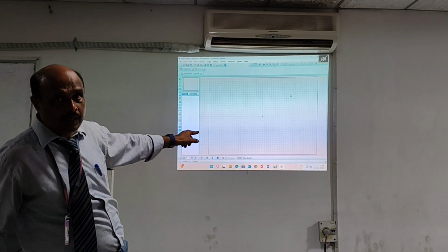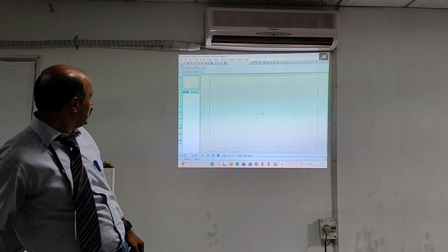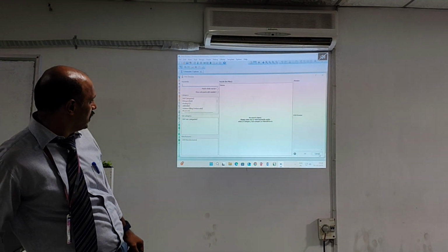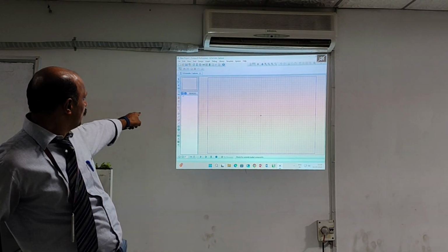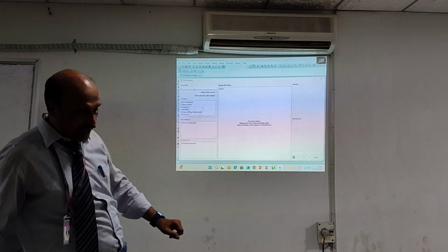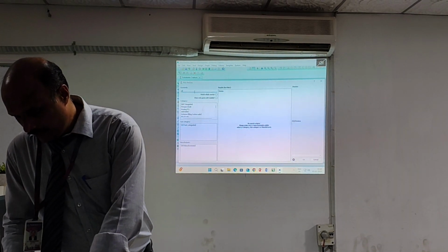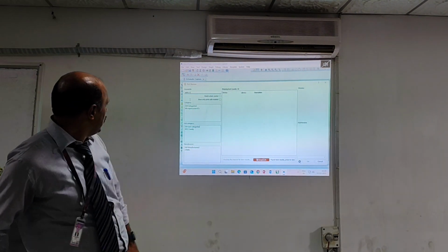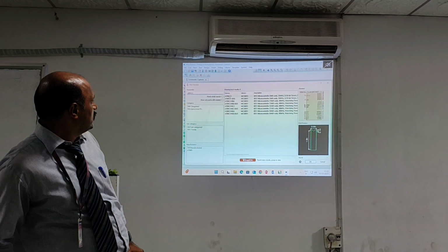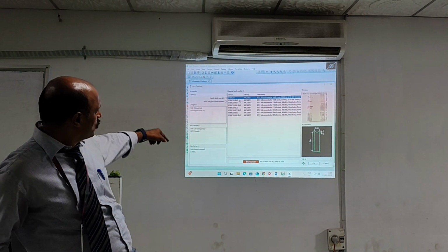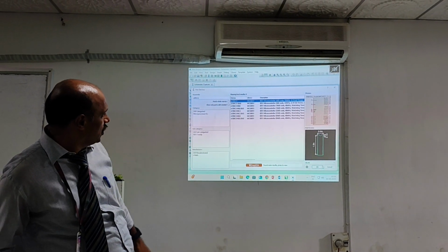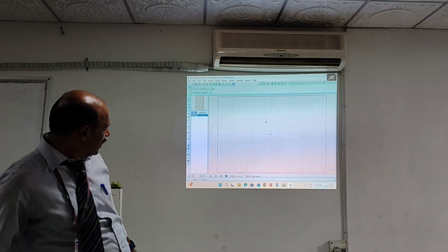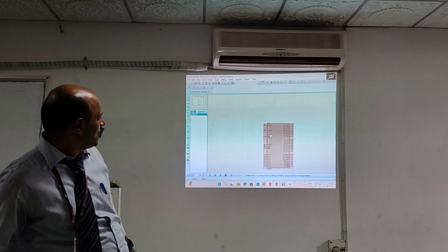Now I have to put the microcontroller into the traffic light signal design. For that, I click the symbol P. Here I put the keyword 89C51. Right. Apart from that you have many options, but you have to select only this one. Okay, now the component is selected. Just by clicking here, the component is placed. You can zoom also.